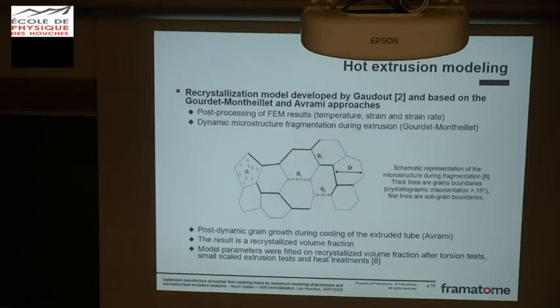And we apply this model in order to predict the recrystallized volume fraction after extrusion and also the grain size. It's a model based on microstructure fragmentation by subgrains with increasing misorientations up to 15 degrees, when we consider it as a new grain boundary and so on. I think you already know this kind of model, so I will not give details.